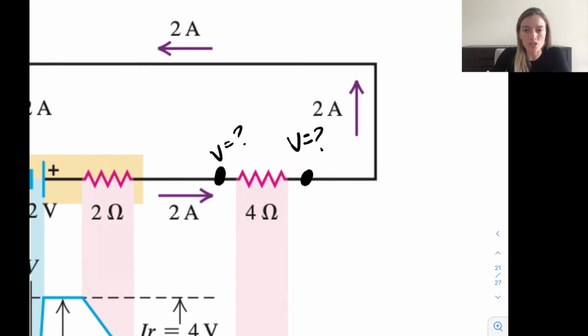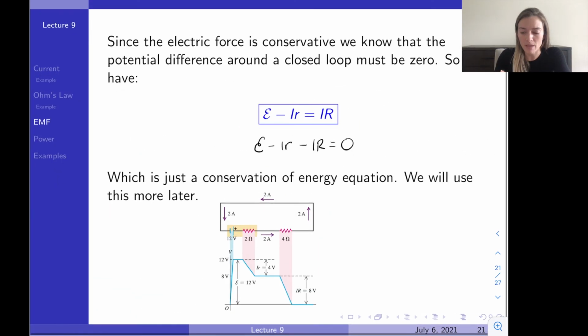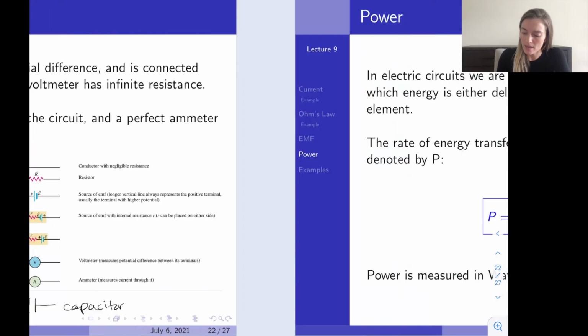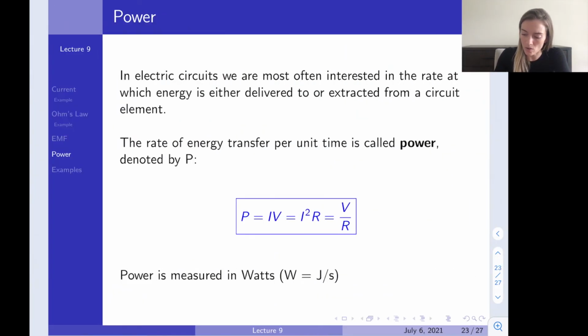That voltage difference you'll multiply by your current, and that will give you the power dissipated through this resistor. We're obviously going to be doing examples with that. So that's how you would find the energy per second dissipated through that resistor. Now, by using this equation and Ohm's law, you can get these other forms of power. And like I said, they're all the same.